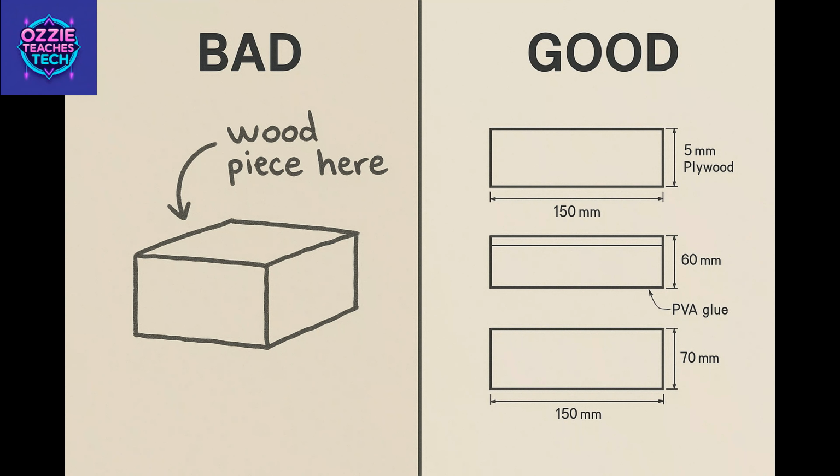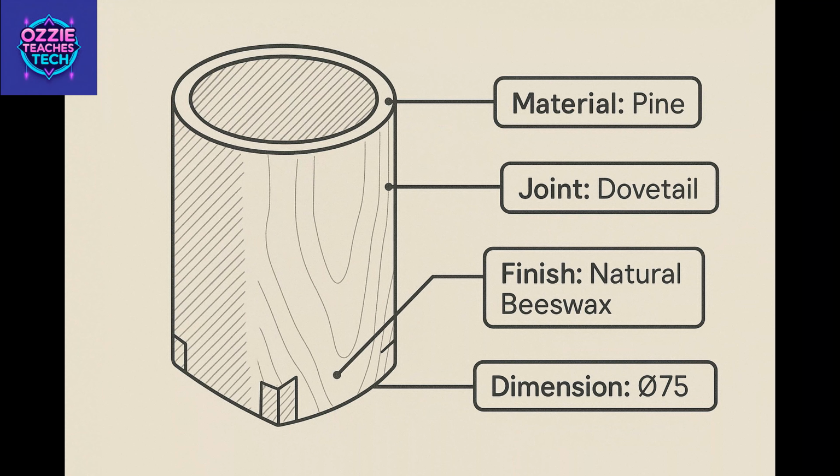2. Add precise measurements. All dimensions should be clearly labeled. Use a consistent unit, could be millimeters, centimeters, or inches. Include angles if relevant. Show thickness of materials. 3. Annotate everything. Label all parts and components. Specify materials for each part. Include joining methods. It could be glue, screws, welding, etc. Add notes about colors, finishes, or textures.